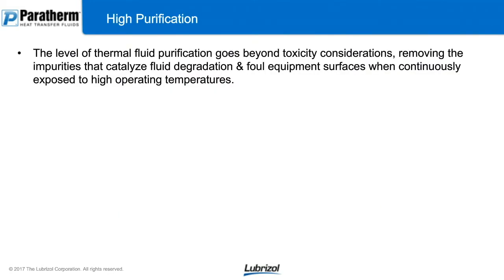So starting off with the first key element, purification. The level of thermal fluid purification is not just about toxicity issues. You want to make sure that you have, we talked earlier about, low levels of impurities. Those impurities are going to catalyze fluid degradation, so they foul out on equipment surfaces much faster than the actual fluid molecules break down.